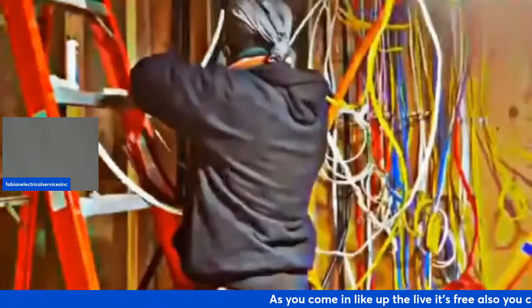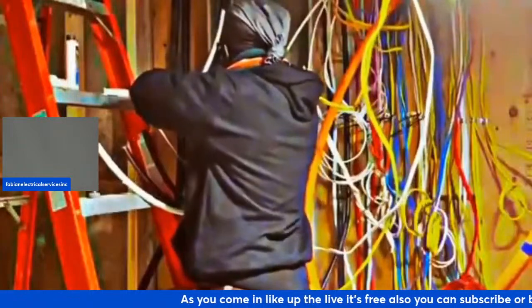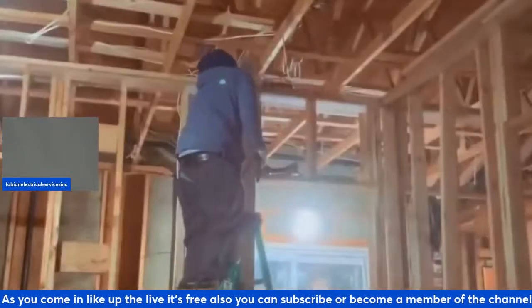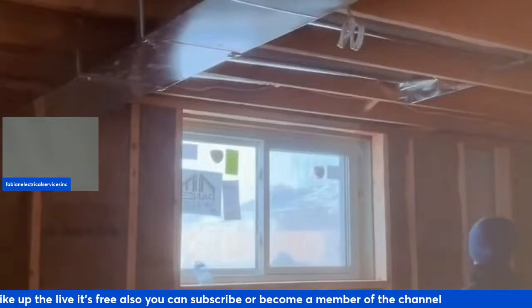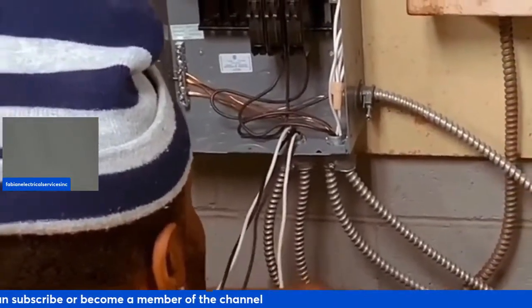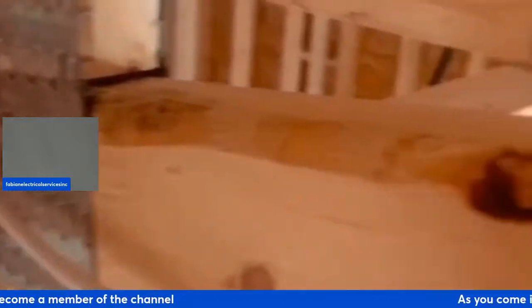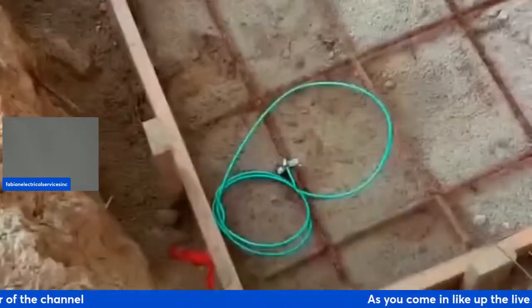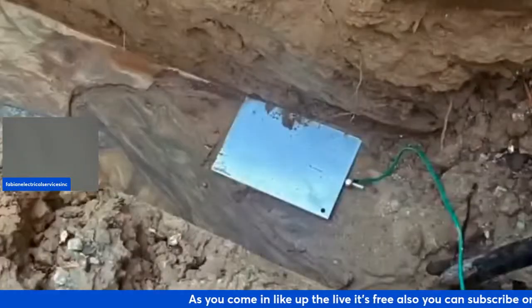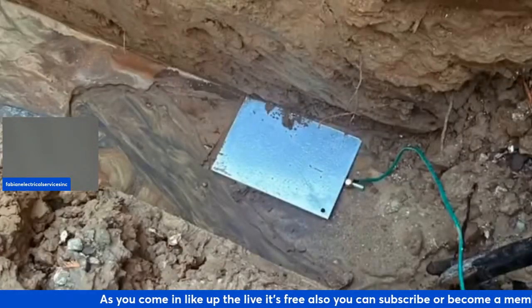So basically what this is saying is an arc fault circuit interrupter is a device that detects dangerous electrical arcs and shuts off the power to prevent fires. It works by distinguishing between harmless normal arcs like those from a switch and dangerous arcs caused by damaged wiring or loose connections, which can generate extreme heat.